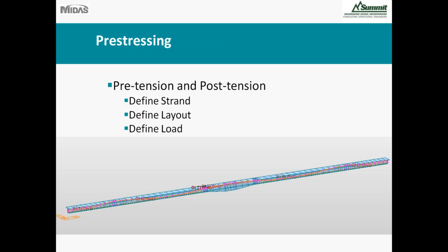For the pre-stressing, we had pre-tensioning in each girder segment and also post-tensioning. And to put that in MIDAS, we defined the strand, defined the PT layout, and then defined the load.